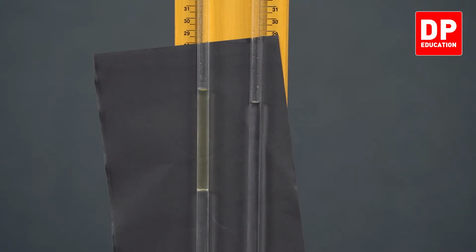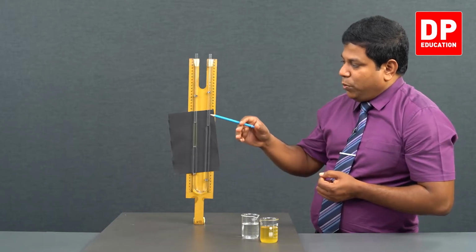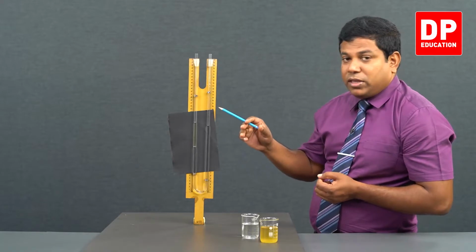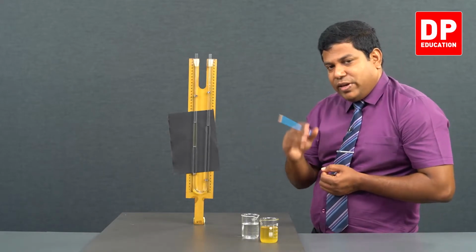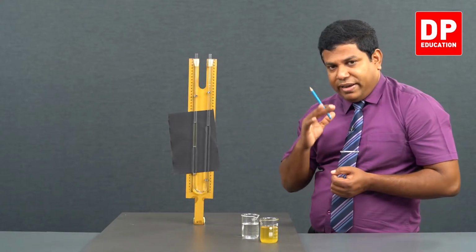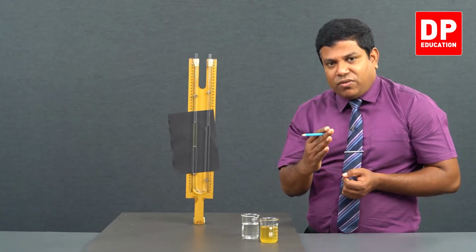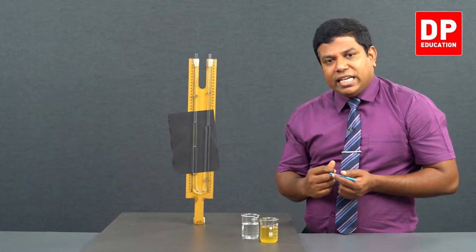Right? That is all the readings we are going to get. So every time we have to take 3 readings, one of the interface, because when you put more oil, the interface will go down and the water will come up on the other side. So all 3 readings we have to take again. 5 times we are going to take readings like this. That means we will have 5 sets of HO and HW readings.